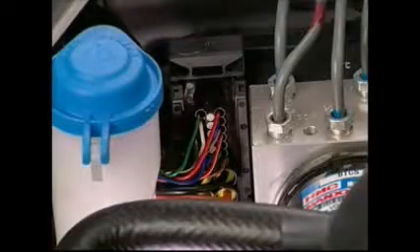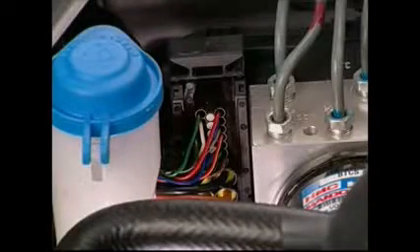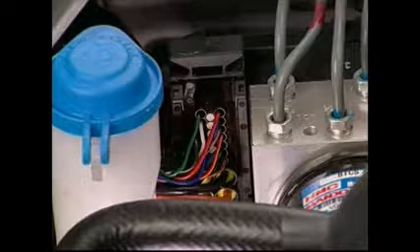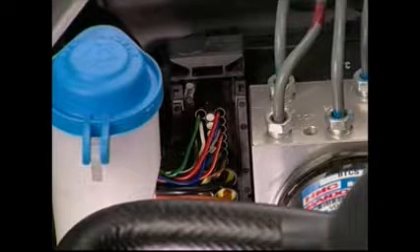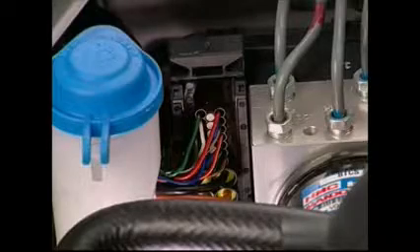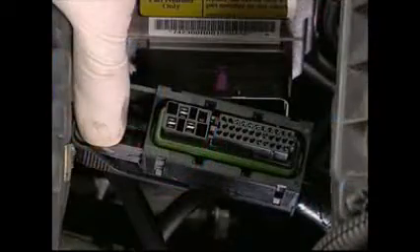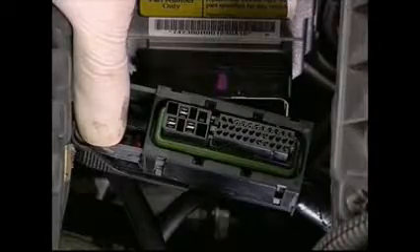Wiring harnesses are connected together by the use of junction blocks. Large junction blocks are often referred to as SMJs, or super multiple junctions. Junction blocks use male and female terminals to connect the wires of the different harnesses and are often bolted together. The terminals in the junction blocks are numbered for identification, either on the block itself or in the repair manual.